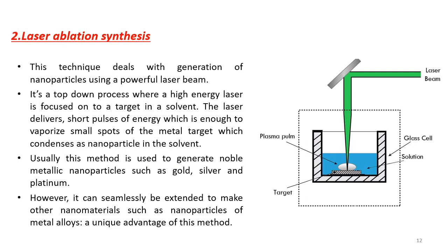The next method of producing nanoparticles using the top-down approach is laser ablation synthesis. As we know, a laser beam can be used for preparing plasma, a higher energy intensity focused beam. So this laser beam can be used for evaporating the target material, like a gold plate, a silver plate, or a platinum plate.